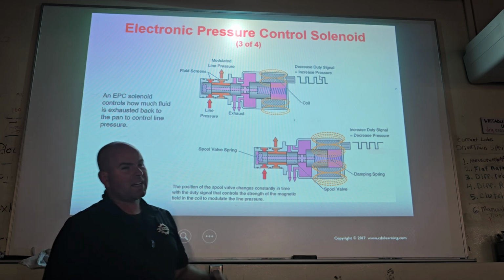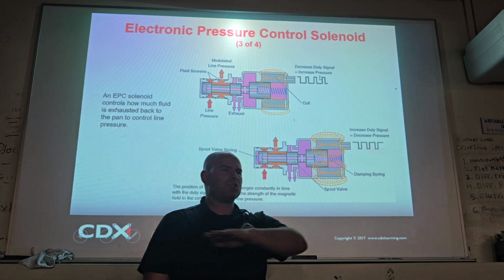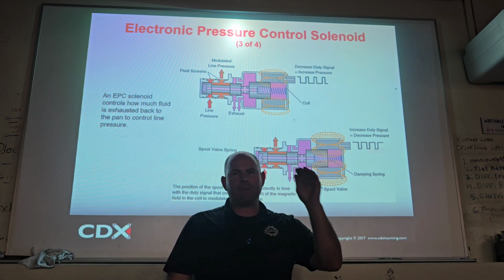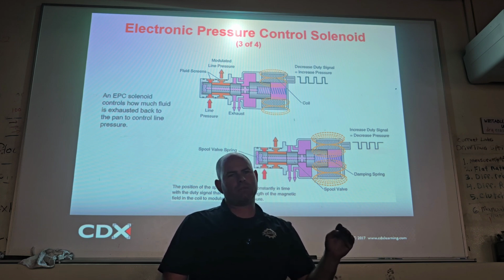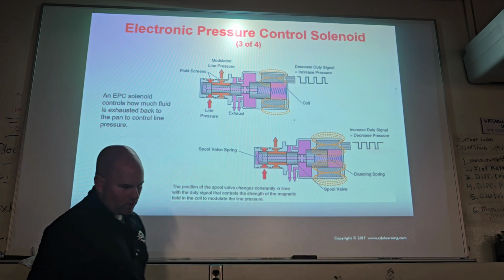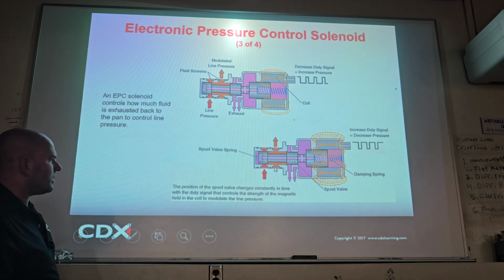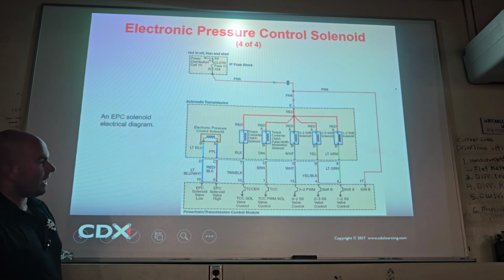So what if you disconnect it? The duty cycle's flatline. That's maximum, maximum, maximum pressure, okay? Maximum. So that's another reason why we'll do it ground control too. It's a better idea. Cool, now increasing the duty cycle is going to decrease the pressure. Cool, that's definitely critical.